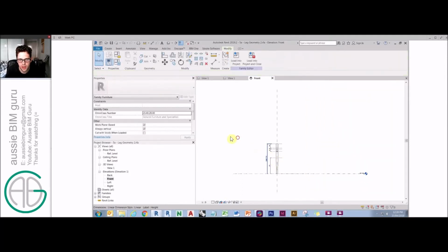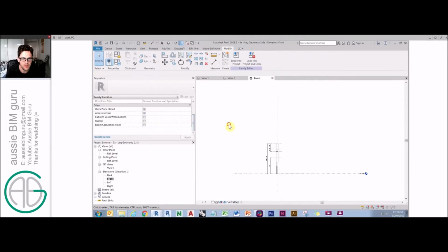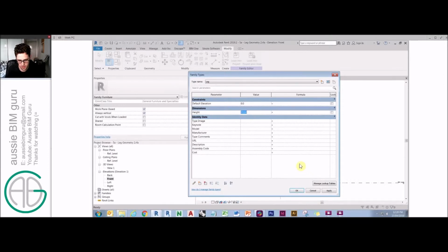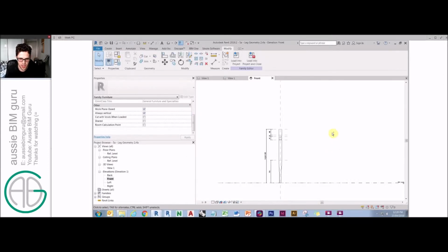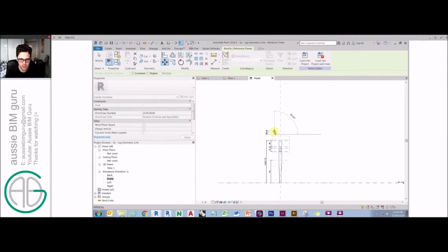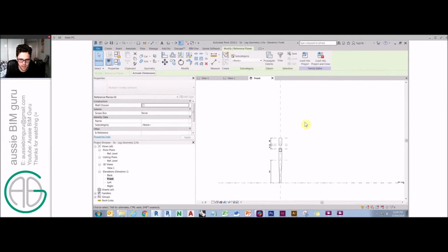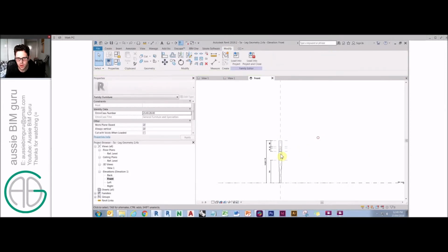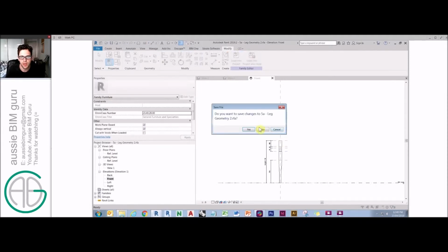That might seem a bit strange, but you'll recall that we didn't make this a shared family. So because these won't reach the project, Revit actually lets you nest instance parameters into type properties of families if they're components, as implausible as that seems on the surface. And you'll see now that if we change that parameter, it now pulls the family with it. We've got to be careful. Sometimes these constraints won't always work if you just manually move things around. Sometimes they do, sometimes they don't. See there? So usually you need to use parameters to pull these because Revit does naturally move this geometry itself the way it thinks it should be done.